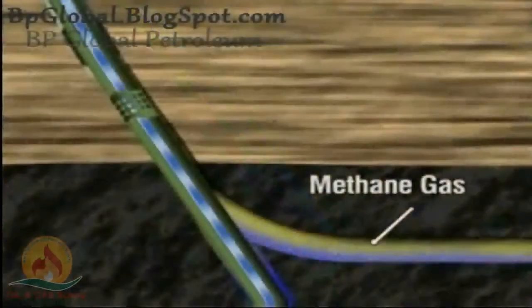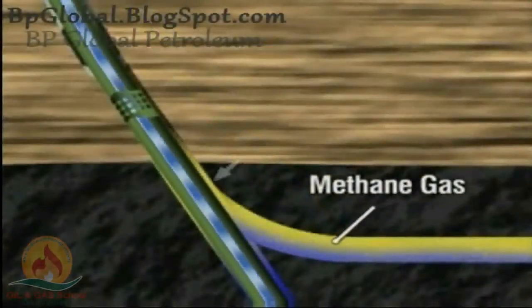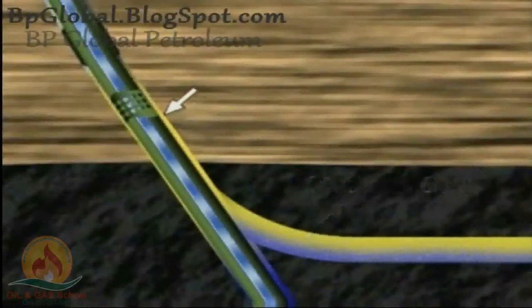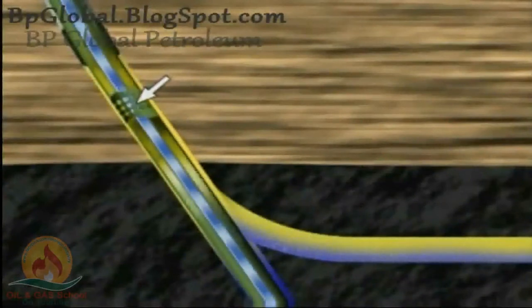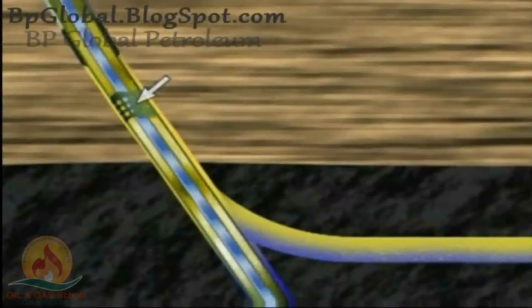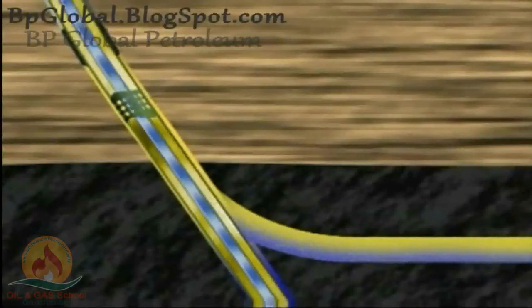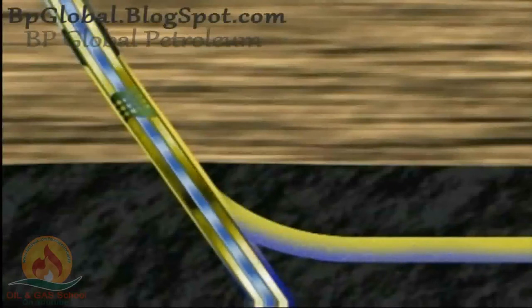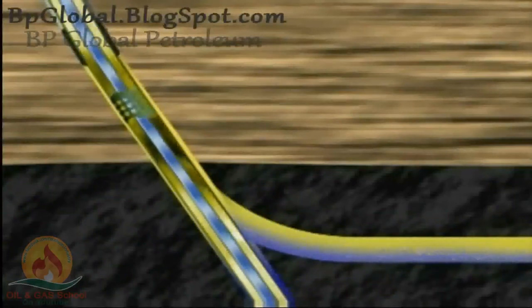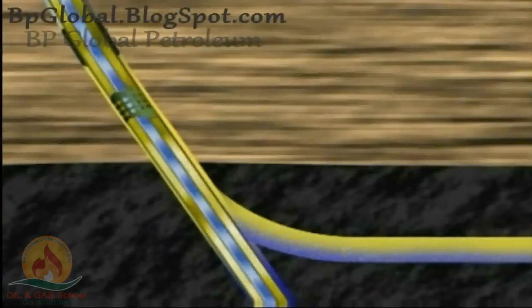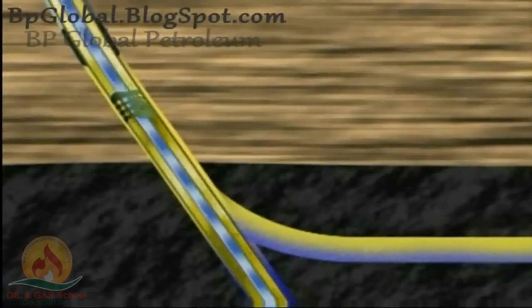After the coal seam begins to dewater, methane gas is released. The gas migrates up and enters the 7-inch casing through the perforations and is pumped to surface via compression. If the formation water is suitable for use, this process is complete. If the water has high salinity and needs to be re-injected, 2 options are available at this point.